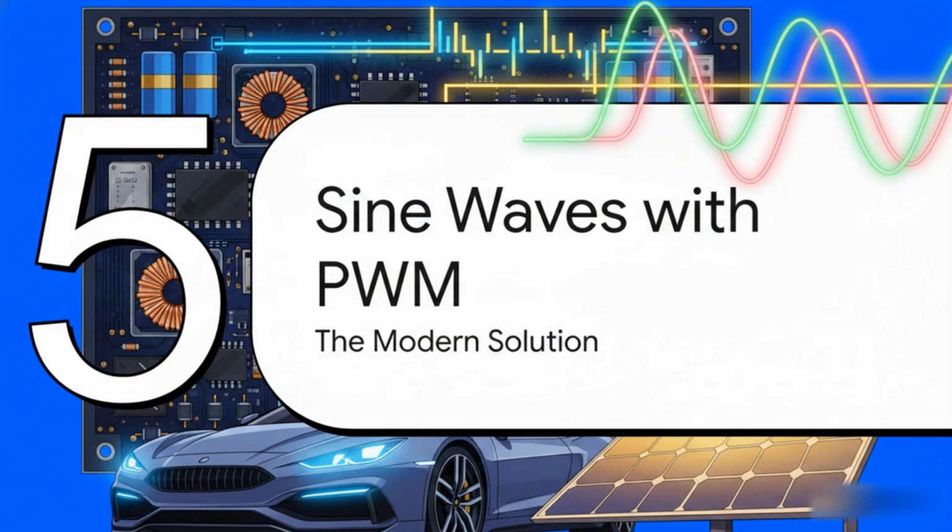Now, the modified square wave is a really clever trick, but it's not perfect. It's great for killing one specific harmonic, but what about the fifth, the seventh, the 11th? To get a truly clean output, we need something much more sophisticated. And that brings us to the technique that is the absolute gold standard today, used in almost every modern high-performance inverter, pulse width modulation, or PWM.